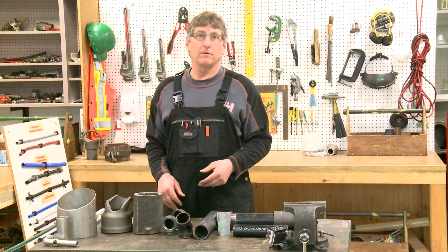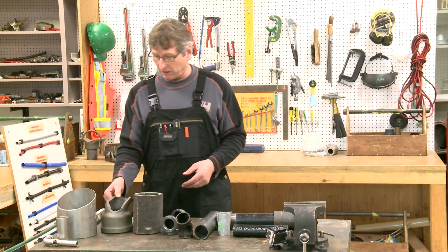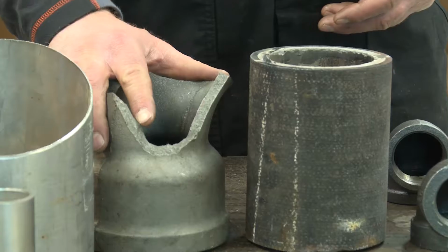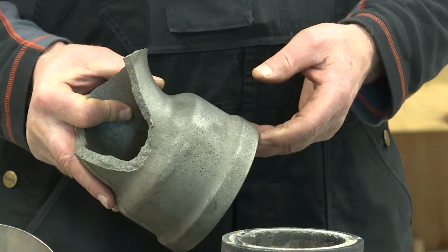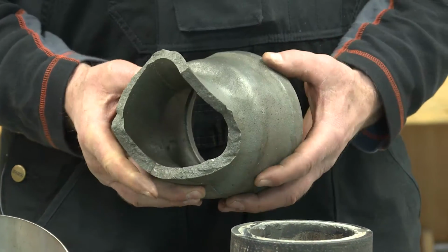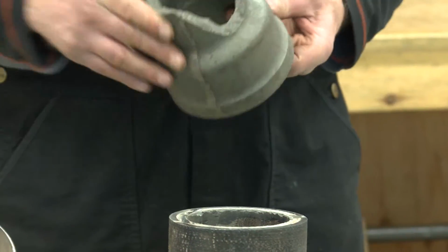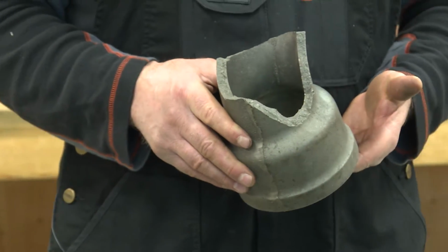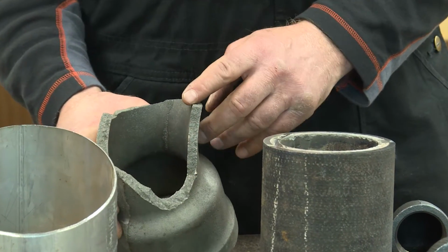Another type of cast iron is silicon iron, also known as Duriron. It's a special type of cast iron with a silicon content over 14%. This gives it very high corrosion resistance for acid waste systems like you'll find in laboratory drainage or correctional facilities where there may be potential for sabotage. You can see the different look that the silicon gives on the edge of this broken fitting.